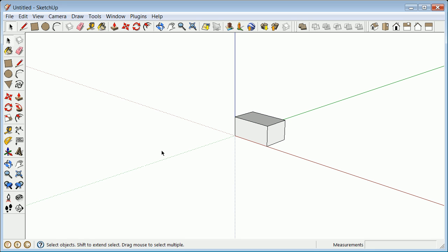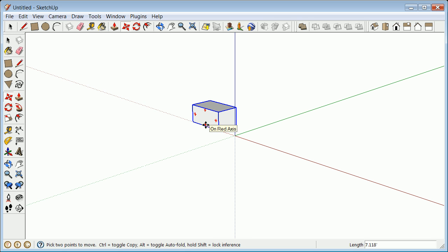All right, a couple more things now. This program works on this rhythm, which is similar to what many of us teach in AutoCAD, and it is this. If you want to do something to something in the drawing, you build a selection set, so left click or window, find the tool you want to do and learn the key in. I think M is move, but I'm going to click on that. Find the place or the side that you want to get a plane for. Hold the shift key, and I'm not going to do that here. I'm just going to move it and slide that over. So then you grab and then move the thing.